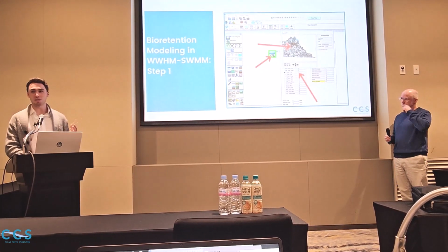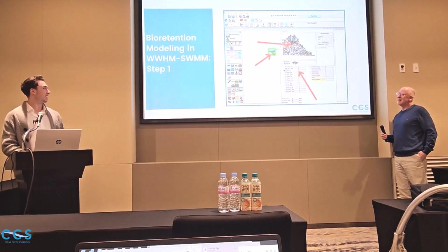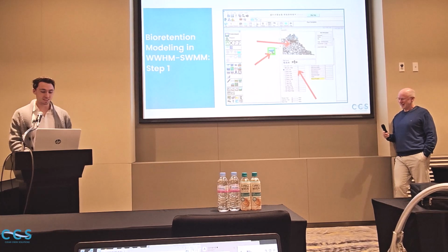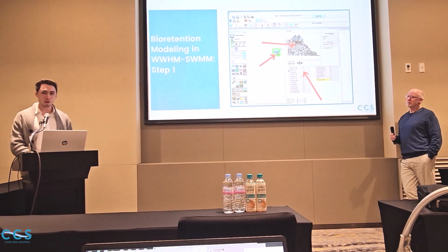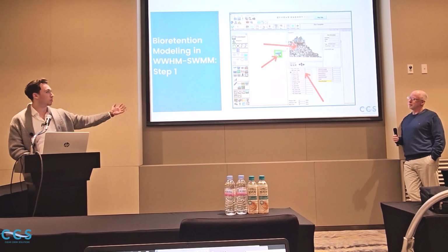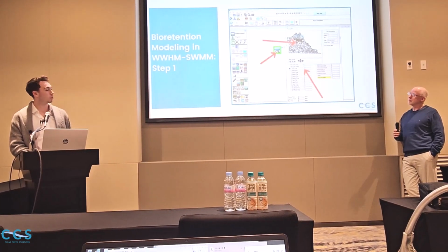And I've been in Korea here for the last week, and in the winter it rains a lot. There is a lot of water. Reminds me of my home state, Washington State. So we have to model the entire hydrologic cycle. We just can't model one stormwater event. So that's why we're utilizing 50 or 60 years of stormwater data in something like SWMM.